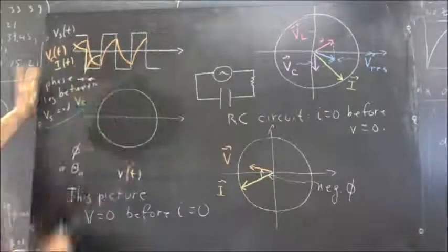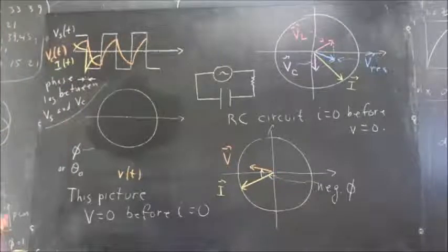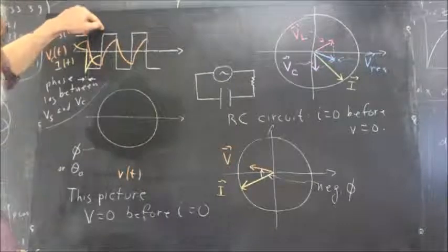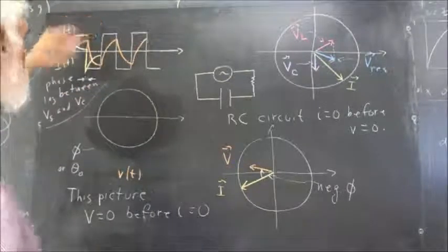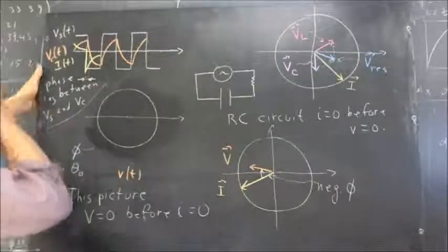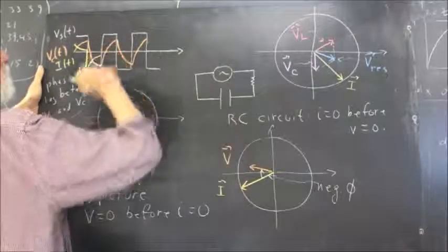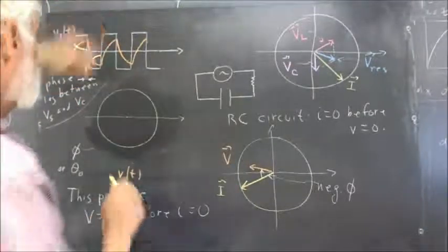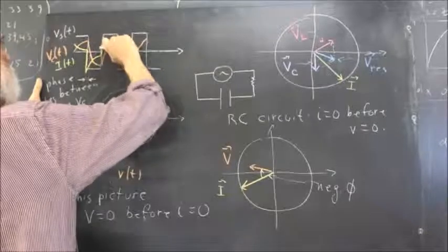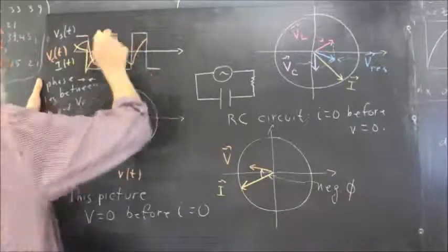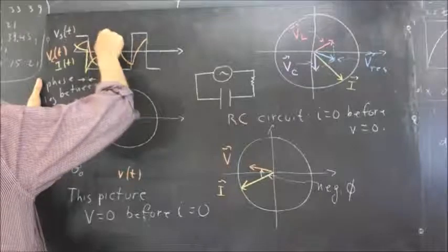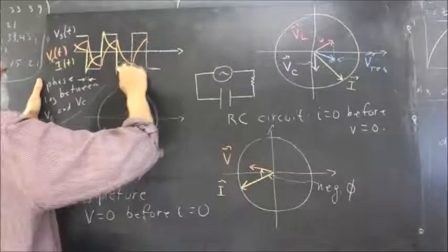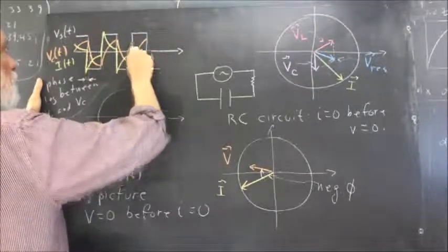It's not going to have time to get as close to zero as it was over here, but it's going to exponentially approach zero. But now you reverse the current again. You have all this capacitor voltage here resisting the increase, and so you have all the capacitor voltage reinforcing the new voltage of the source. And you're going to, again, spike up here. And then the current is going to exponentially approach zero until you spike down here again, and so forth.